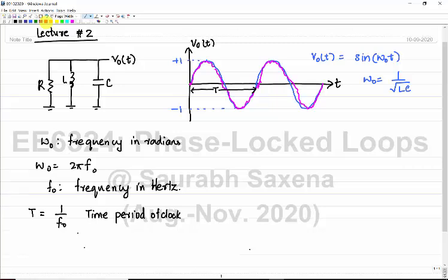Okay, and why do you get this waveform? Because there are noisy elements in the circuit. Okay, so it's like, see, if you have this resistor, then you cannot get a fixed sine wave output, so you are going to add some other kind of circuit in parallel or somehow, such that you always get a sustained sine wave, maybe of roughly the same amplitude.